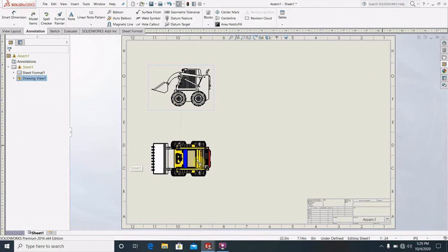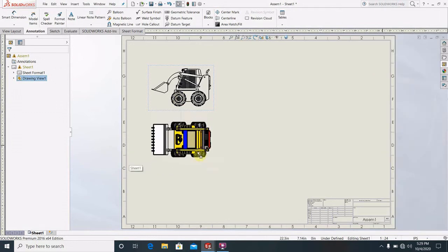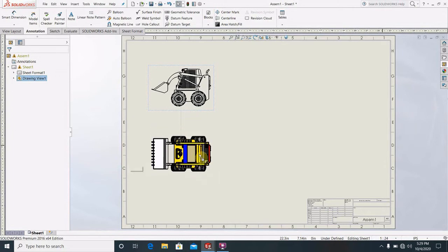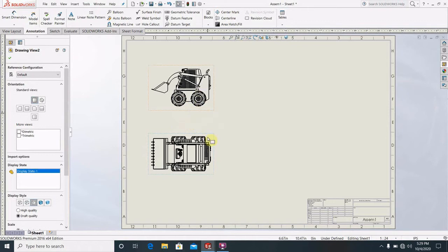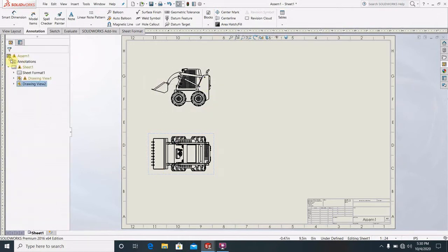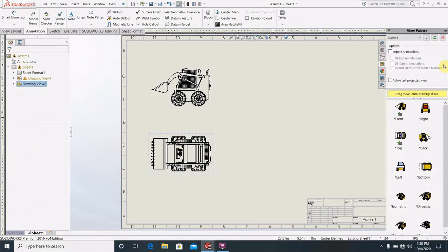If you drag it to the top view, one line automatically comes, that is the plan elevation model, and the same dimension is automatically applied. Then if you go here, that is the right view, I think.